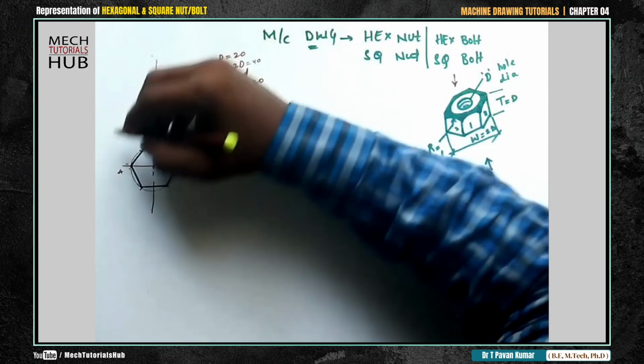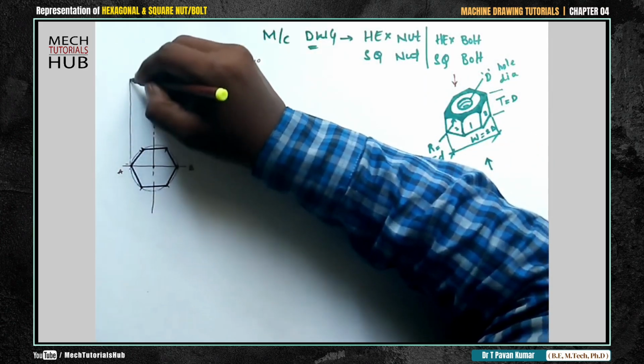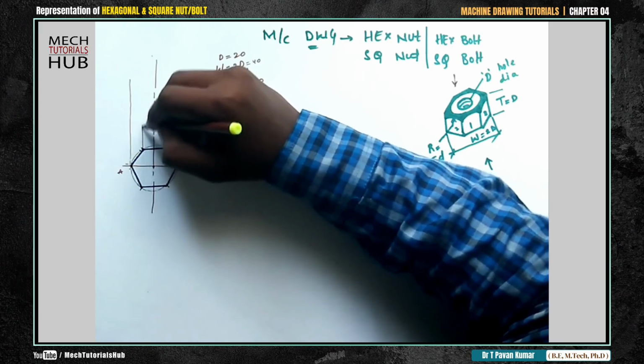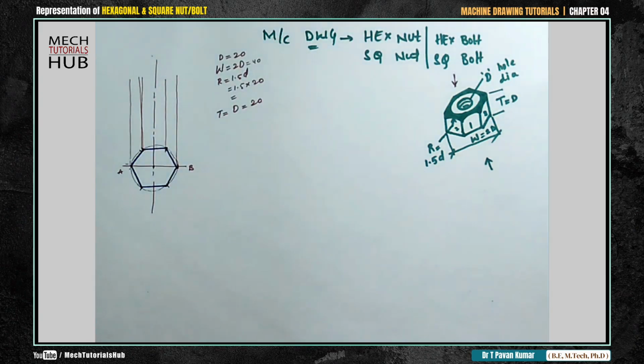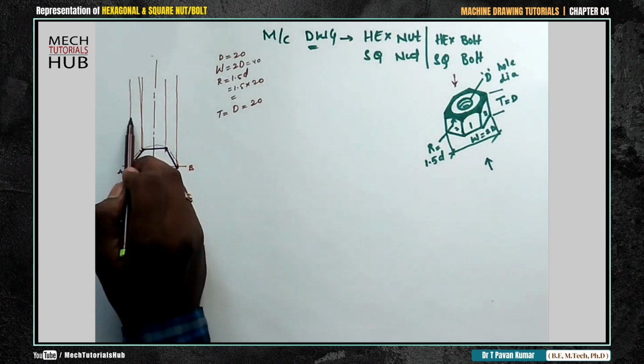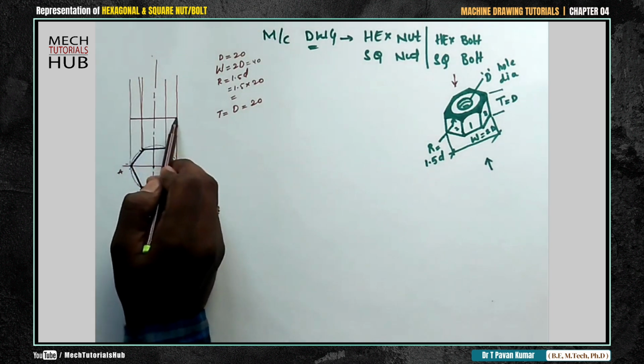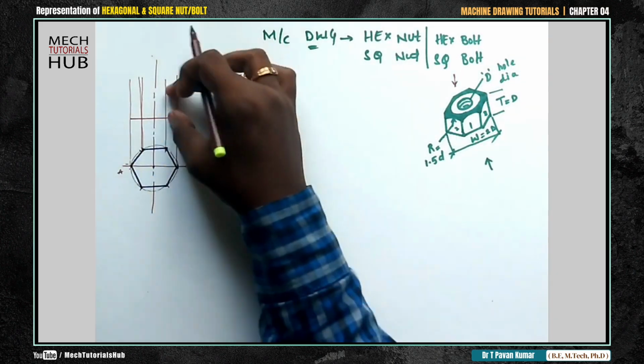Try to project them all above. Project line 1 to draw the front view, then 2, 3, 4. Let us make it straight, up to some infinite distance. After this, take any horizontal somewhere away from the top view. Somewhere away, take one horizontal. Now try to place the front view.